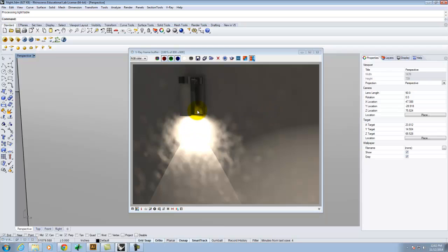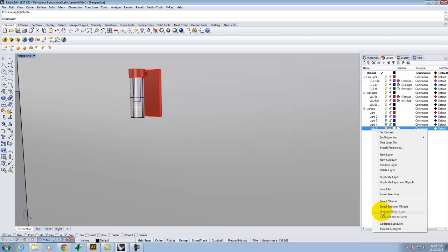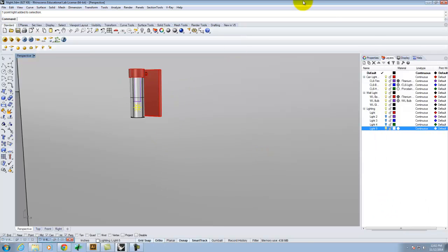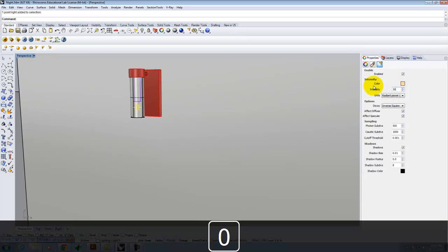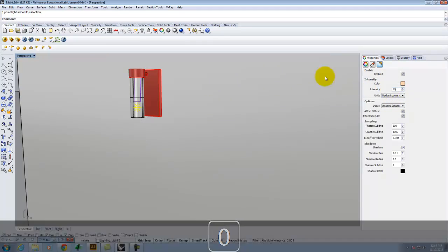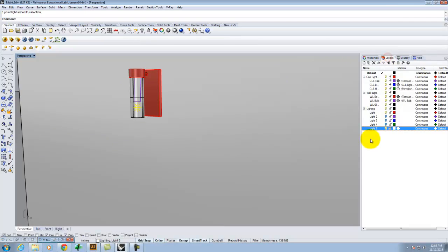So we're getting a lot of light out of the bottom. The transparent glass isn't doing what we want it to do. So we may have to play around with things a little bit to see if we can get it better. I think number one, the intensity of the light is too much. So let me go to layers. One of the advantages is I can select objects by layer because I put it on its own layer. Let's change a few things. Let's go down to maybe a 30 watt, inverse square radiant power. Let me make sure I am on correct settings. Okay, that's good. I'm going to go into my layers and temporarily I'm going to hide my...